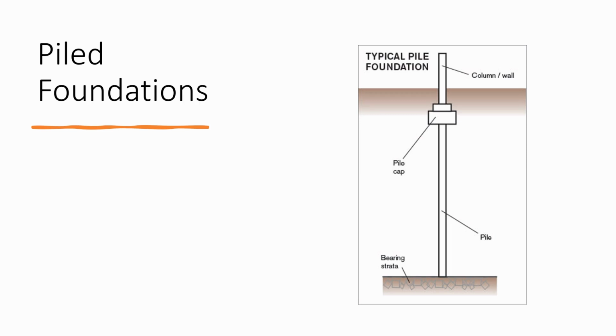They are typically used for large structures like the one we're going to encounter in this project, and in situations where soil is not suitable to prevent excessive settlement. It's also beneficial to use a pile foundation when the groundwater table is high, as again linking back to the project brief, we do encounter a water table at 1.2 metres.